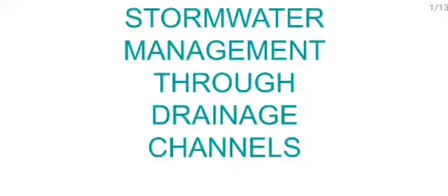The risk of failure of the slopes can be reduced to a greater extent by proper management of runoff, especially through drains.